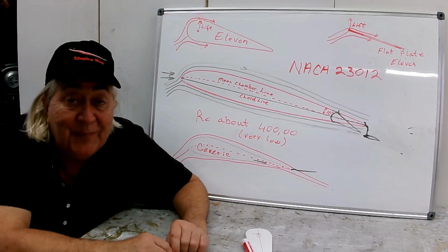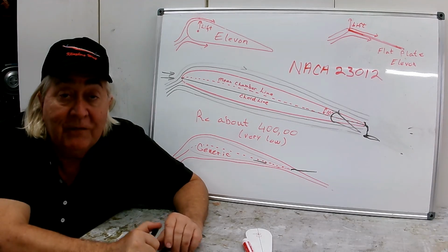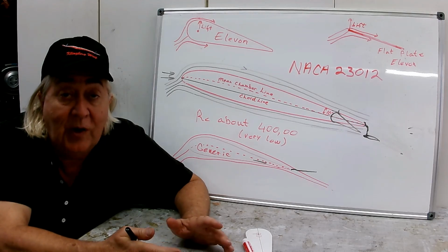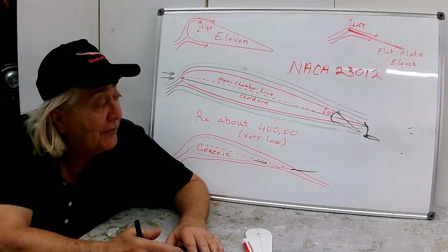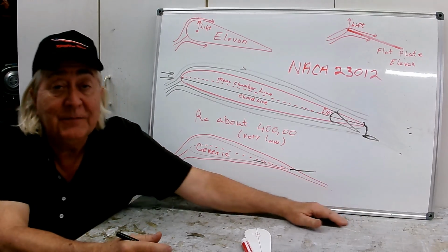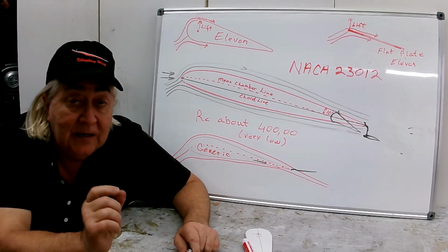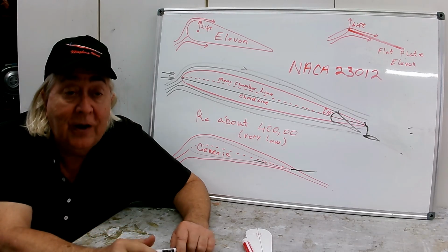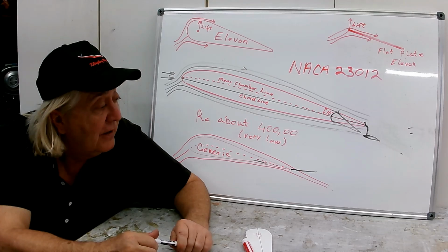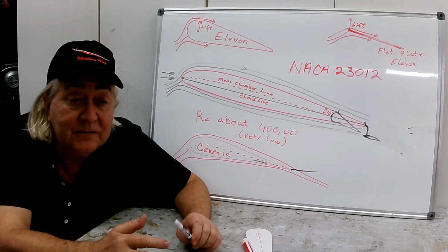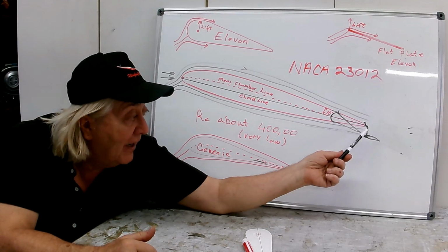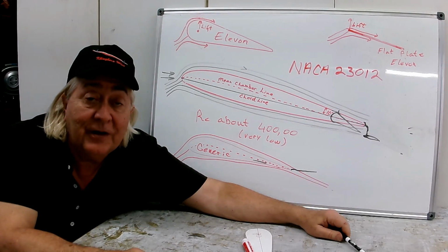On the Mitchell wing, not a big deal, because standard Rogallo wings are flying around at 4-to-1 glide ratio. Mitchell wing comes along and does 10 or 12. It's like, wow, you tripled the glide ratio. So you got some more drag. So what? You're still doing 3 times better than everybody else. If we're up around 30-to-1, which is where I want to be, and regular hang gliders are flying, like an Atos might do 20-to-1. Oh, this extra drag's a big deal, especially when you want to go fast.